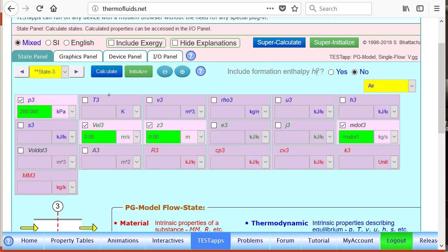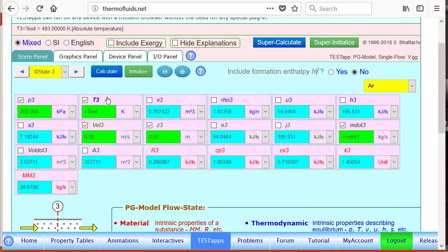So here we could write temperature equals T-exit. So what's the benefit of that? Instead of typing in 220 degrees Celsius here, the benefit is that we could later go and change the T-exit, and we don't have to come to the details here and update all calculations. Okay, so now we have all 3 states calculated.